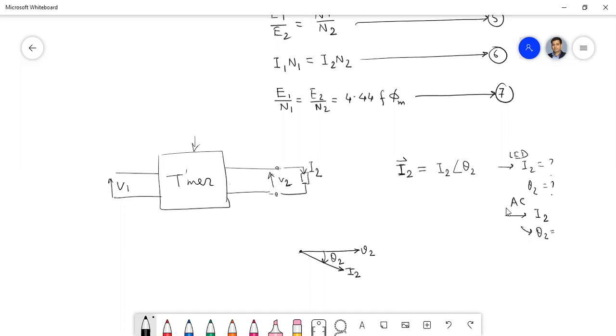because the air conditioner has a motor, and the motor consists of several coils inside it. We don't know the exact thing which is inside the AC, but we can say that it has a motor, and a motor consists of several coils. And if there are coils, it means there is inductance. But in an LED lamp we have very little inductance. So if we have large inductance in some device, we'll get a high theta.